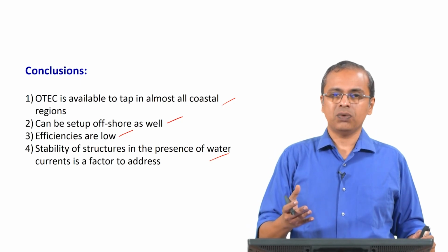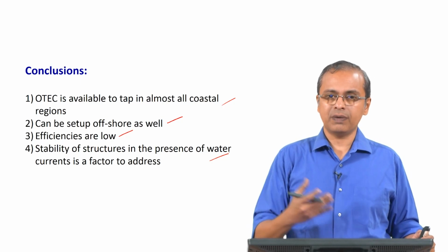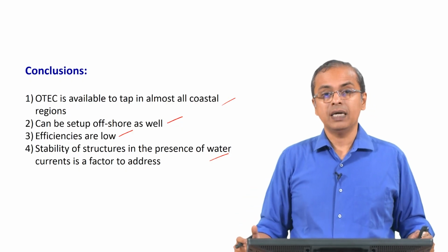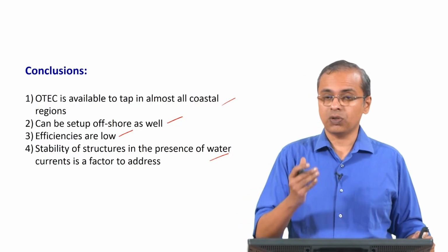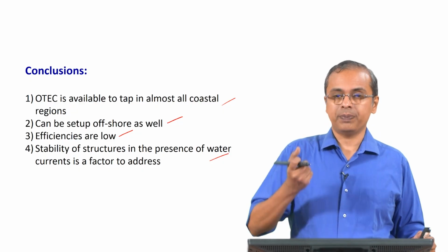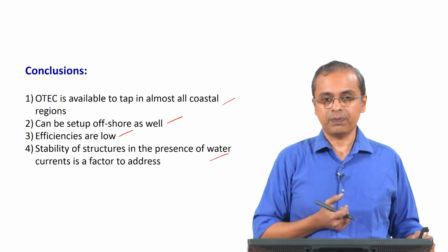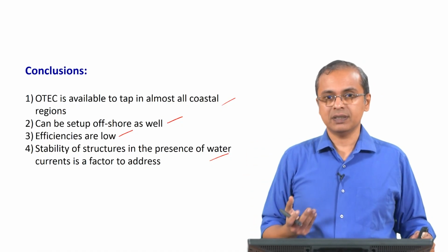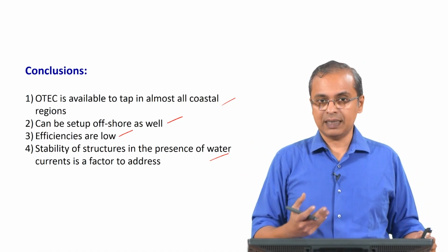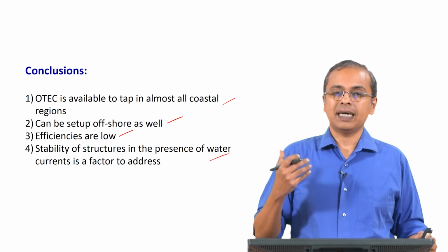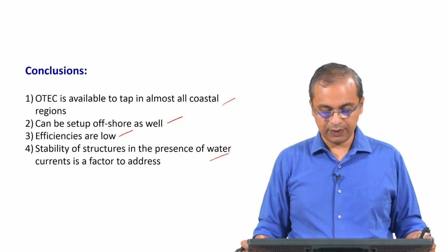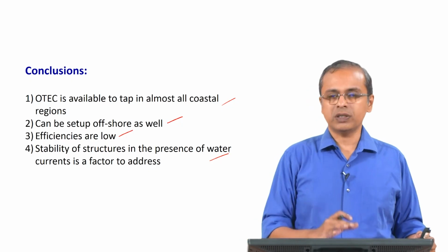Even with all the piping, you are using salty water, so you have to make sure that corrosion is not an issue. It is not just salty water, it is flowing salty water. You are pumping up water, so it is going to flow. So, you are also going to have some abrasion of the surfaces, and so the materials should be abrasion resistant and should not corrode even if there is abrasion in these salty water conditions. So, these are some of the challenges.